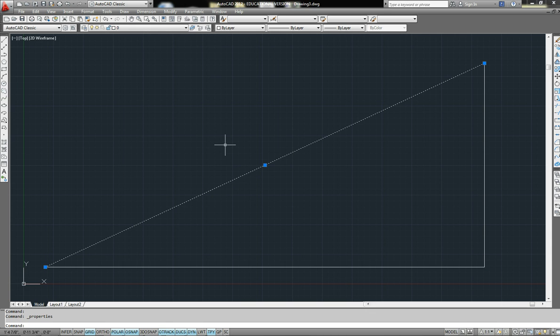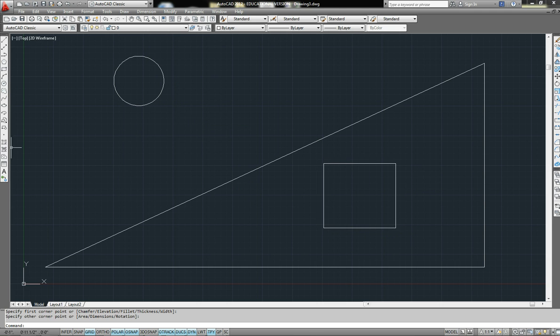An object is any part of your drawing. In this case here, the circle is an object. I could make a rectangle here an object. I can have another line going this way. Each one of these things is separate objects. When I want to select different objects, there's a couple different ways of doing it. If I want to select multiple objects for any reason, I can click on them one at a time. And I can keep clicking on them, and that'll keep selecting objects. If I want to deselect them, I can hit the escape button on the top left of my keyboard.